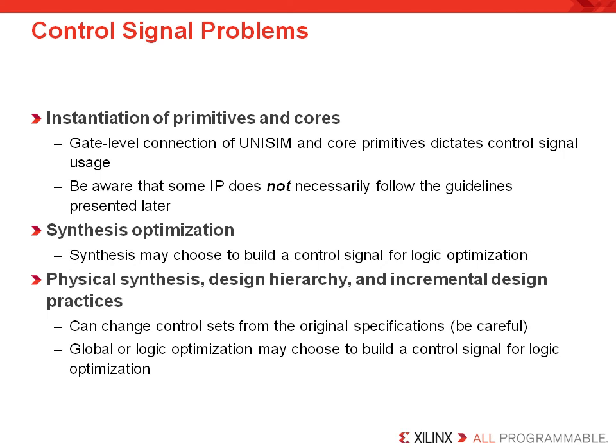When planning your control signal usage for your flip-flops, keep in mind that the instantiation of cores or IP will also add additional control signals to your design. This is often forgotten by designers. So you have to first build your cores and look at the control signals you need in building those cores, and then you want to plan on trying to share those same control signals with as much of the HDL as possible. So try to share them, and we recommend that you build and simulate your IP as soon as possible from construction so you can plan on sharing your control signals appropriately.